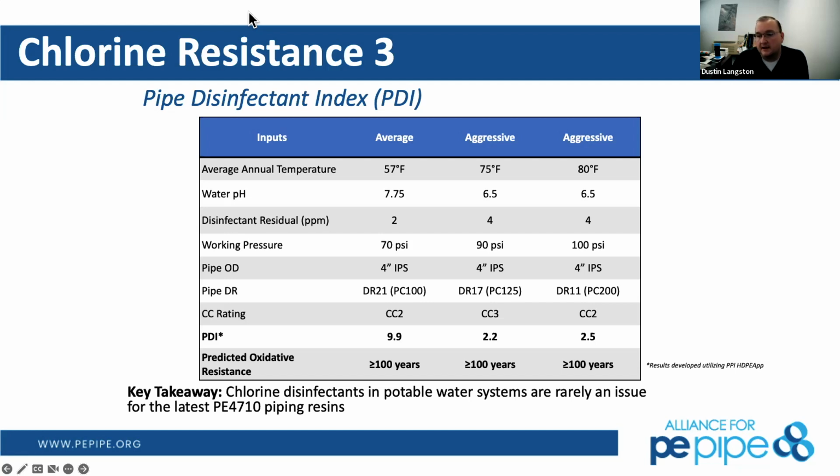But usually in a full-on distribution system, if you're using chlorine dioxide, we don't recommend using polyethylene. And it eats up gaskets and other materials. It's also, well, it eats everything. It eats metallics, it eats fittings. Chlorine dioxide is super aggressive.